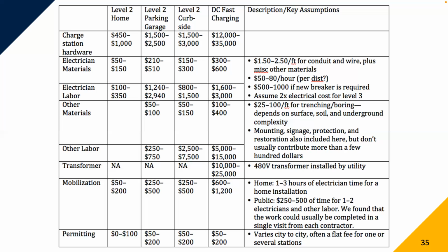And as batteries operate in that buffer range, it's a lot more robust to issues related to faster charging, higher temperatures, that sort of thing. The degradation is substantially decreased. So if you only charge your electric vehicle on 50 kilowatt all the time and you subject it to these heavy duty cycles, the degradation will be accelerated for sure.